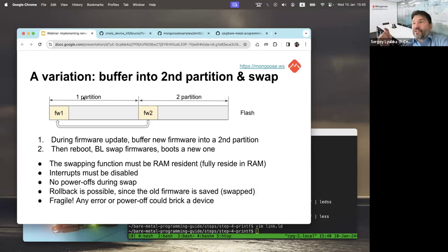If that flag is not changed during this 2 minute timer interval, then the bootloader triggers the timer. And if the flag is still not modified, that means that something is wrong with the firmware. Nobody or nothing has set this flag to verified. Neither a human set it to verified, nor firmware code or some automatic code. So maybe there is something wrong. Maybe the firmware hung or went into an infinite loop or crashed or whatever happens with this, right?